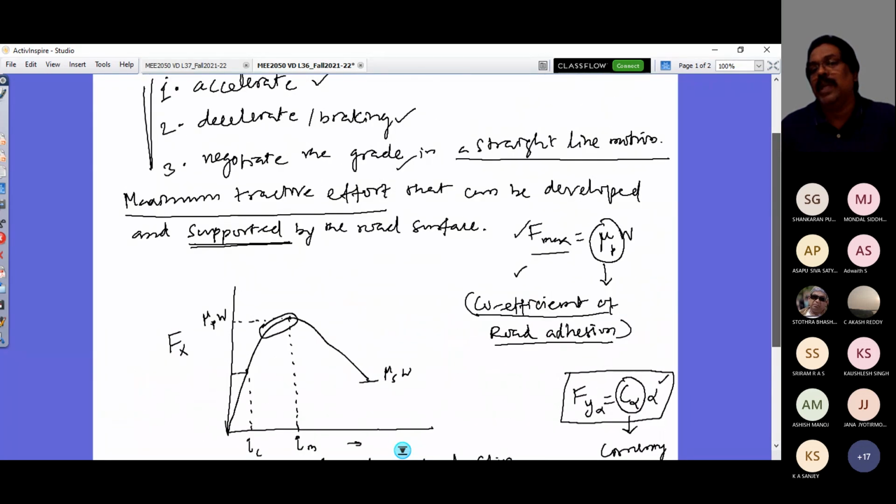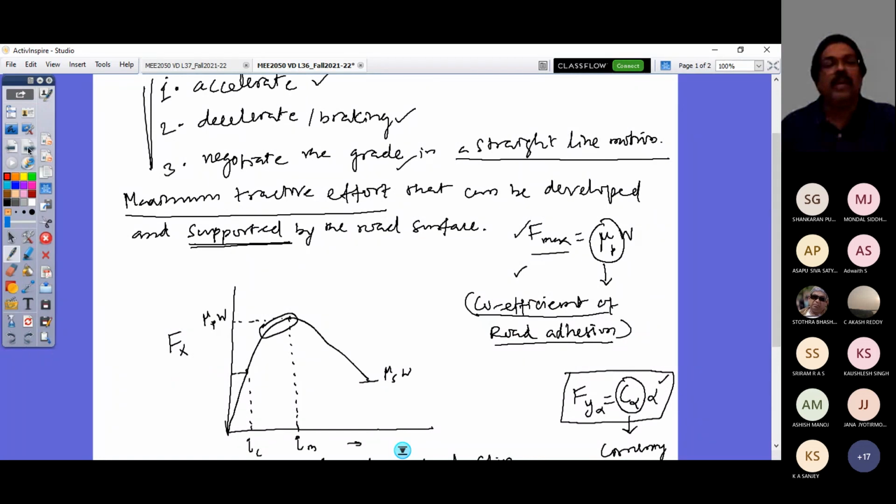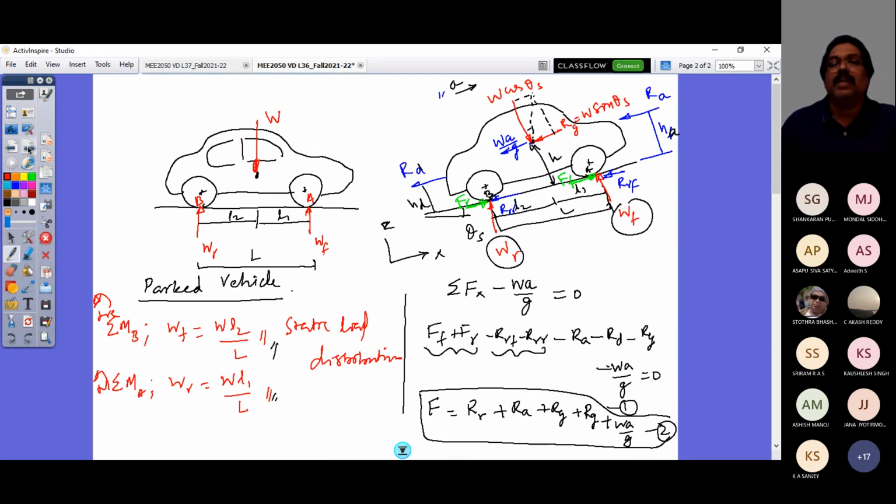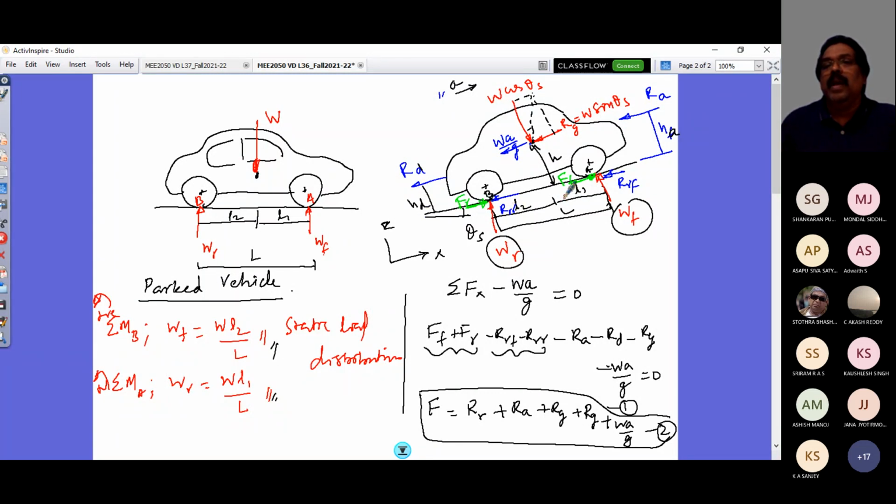With this understanding of the effects as a function of longitudinal slip, we looked at the free body diagram of a passenger car and all the external forces acting on the vehicle as it accelerates up the slope. Since it is accelerating up the slope, there is D'Alembert's force, which is an inertia force introduced for the dynamic equilibrium of the vehicle.